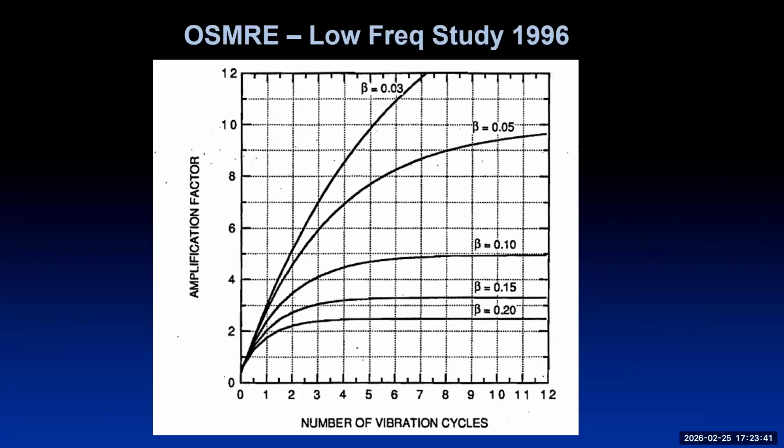0.5%. And that was under excitation; we had a big pendulum and a hydraulic actuator working on that. The natural frequency of the chimney that we were testing was 0.462 hertz, and the damping was 0.5%. So it agreed fairly well with the estimate of what the nonlinear damping should be.